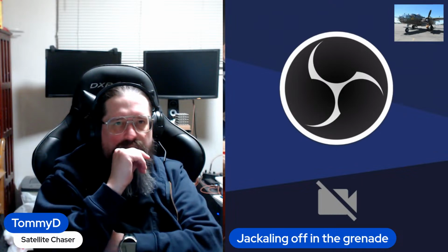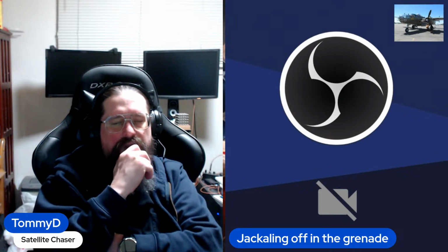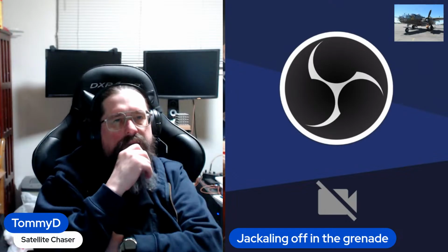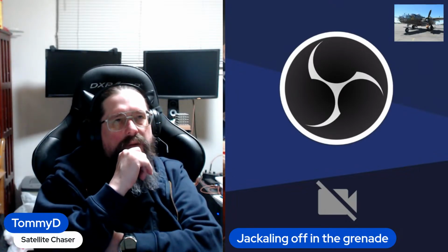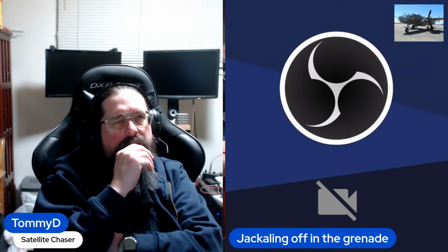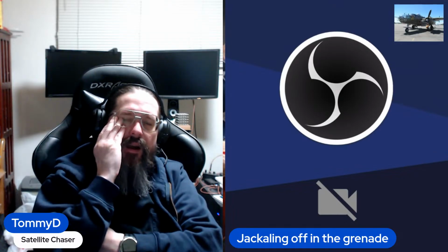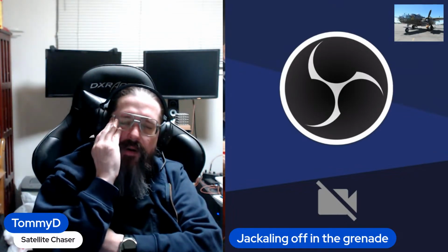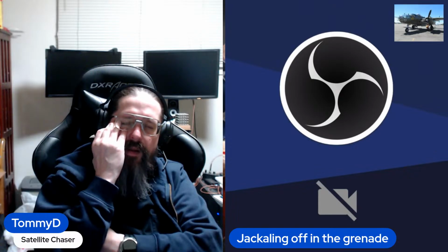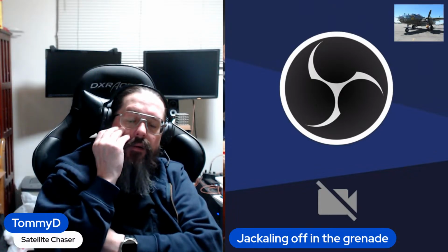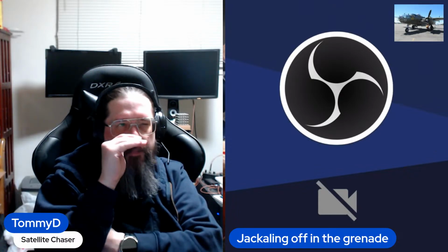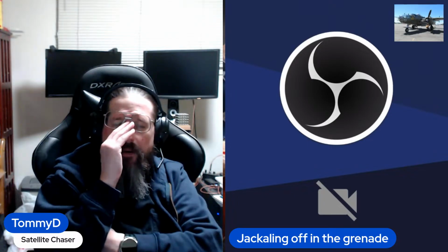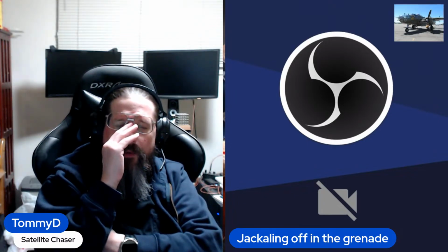When you transform that into a DC voltage, you've got loss. You've got heat. You can get around it with a bridge rectifier, and that's what most converters for AC to DC do. And then you get a ripple current, and you have to smooth that out too.